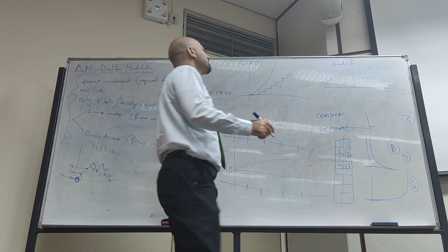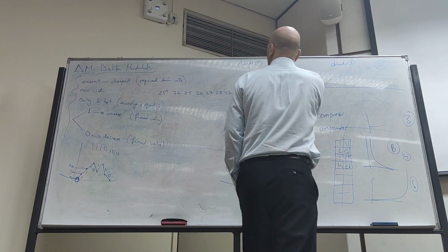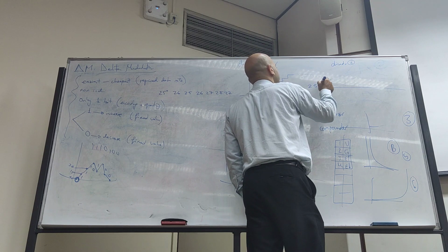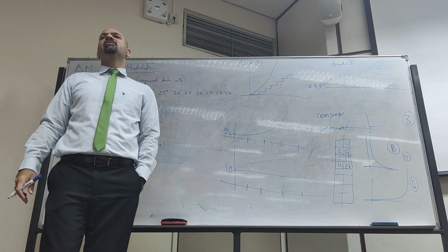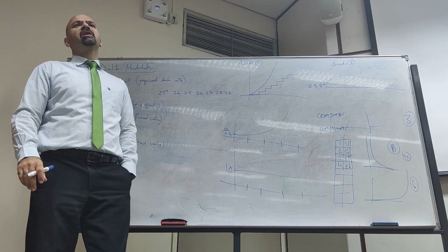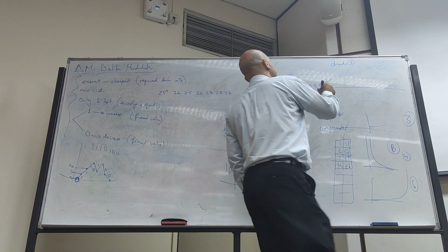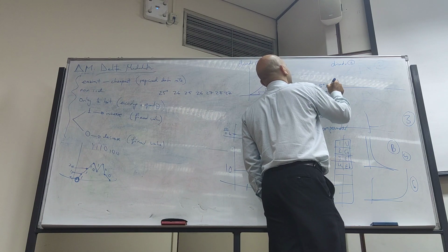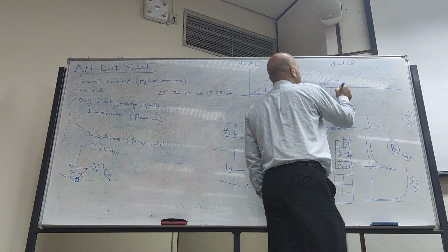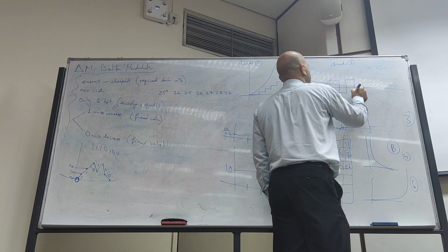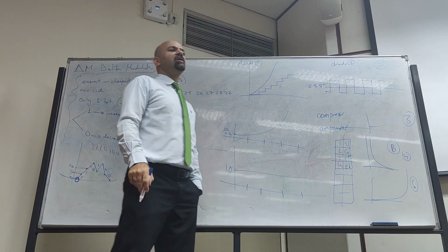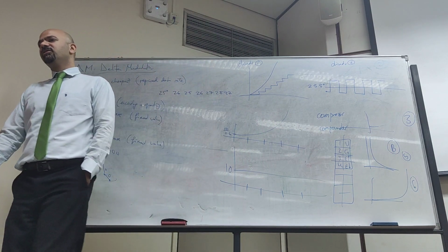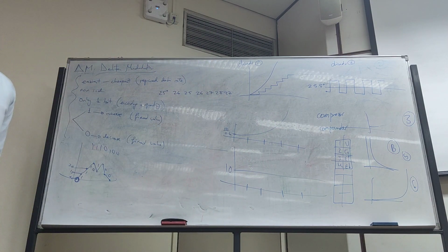That's it. So here, imagine this is fixed at how much you want to say. This is the example, 25.5. The temperature is 25.5. What will the system do? It will become crazy. Imagine it is at 25, then it will say increase to 26. Decrease to 25. Increase, decrease, increase, decrease, and so on. So here, we will say that the system went into a ping-pong effect. It cannot fix itself.